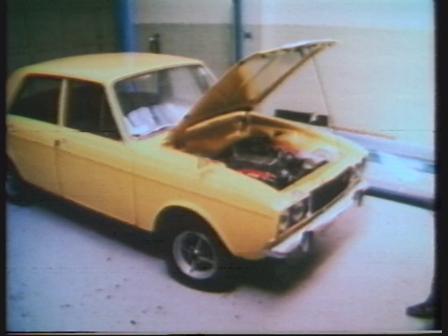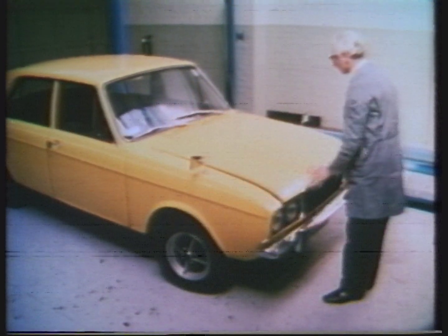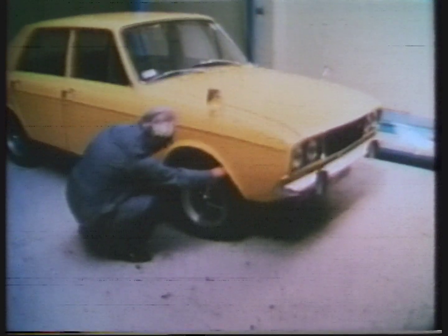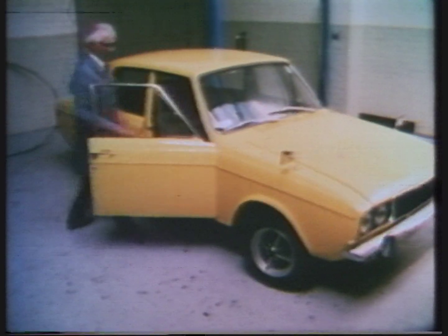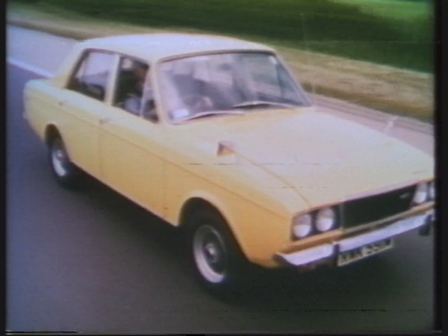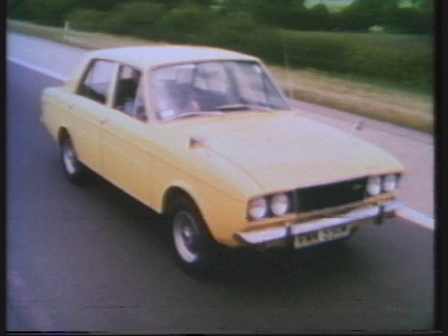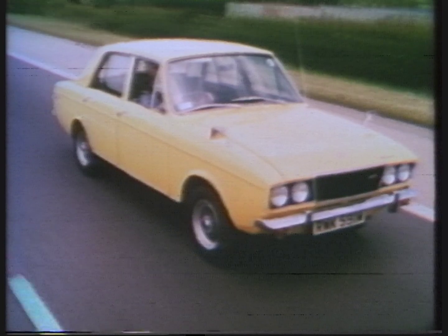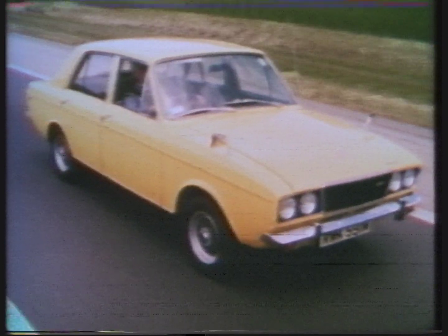When you're preparing for road test, in addition to all usual checks, bear in mind the reasons for the particular test. Then, when you go out on the road, you'll already know something of the mechanical condition of parts of the vehicle that may come in question. Remember, the test is to prove or disprove the elimination of objectionable vibration. It must cover the ranges under which the vibration complained about occurred. If remaining vibration is found on subsequent tests, it must be described and identified so that the workshop moves in the right direction to effect a cure.